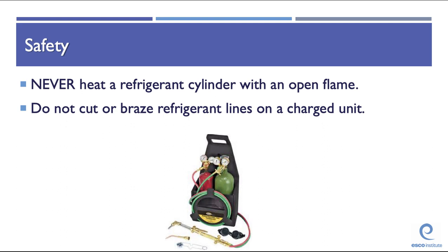If a hydrocarbon refrigerant is released into a space, an explosion can occur if the refrigerant concentration is above the lower flammability limit and below the upper flammability limit with an ignition source. That's hydrocarbon refrigerants. That's the propane type refrigerants.